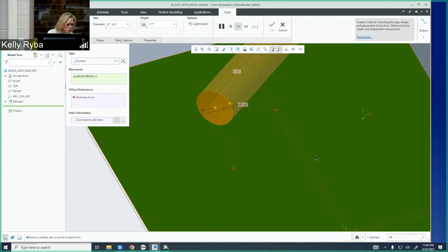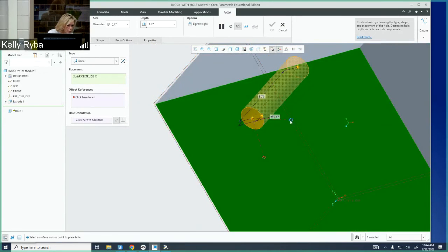Now, I'm going to zoom out here a little bit, and I'm going to go over the top of this diamond, and it activates to be blue. I'm going to click, and I'm going to drag over to where it now becomes a connected diamond, and I'm going to release, and it's going to recognize that edge. Did you see what I did there? And now I can double click that 3.13, and I'm going to make it 2.5, enter. And it positions it in that direction.